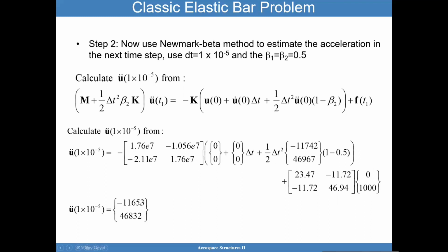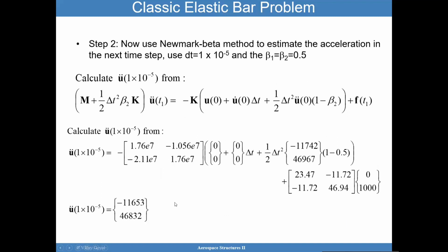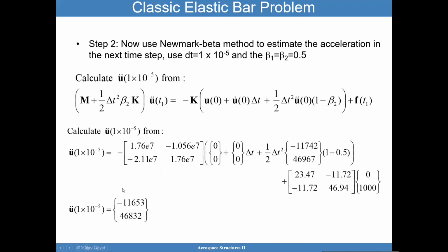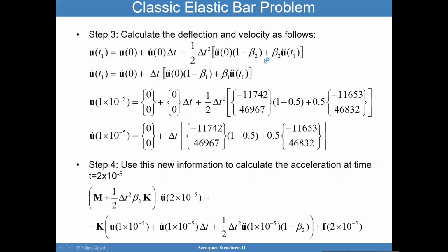So I've marched the solution forward just a little bit. You can see the accelerations didn't change very much. But I still calculate what that looks like. And so now that I know the accelerations at this time step, and I know the accelerations at time equals 0, I can then go ahead and plug it in here. Beta 2 was taken as 1/2.